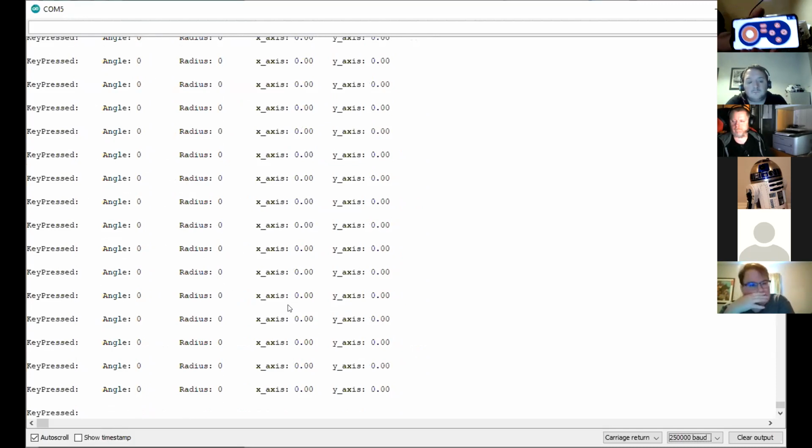So just stepping back now, all we've really done is connected 4 wires between an Arduino and a Bluetooth, loaded an app on the phone and loaded an example code. And what you've now got is a joystick that's actually controlling the Arduino. It's not doing anything at the moment, as in the Arduino is not then controlling a servo or a motor. But if you wanted to introduce Bluetooth control into any of your projects, it's very easy. There's lots of these kind of things that kick around that do that. And things like triggering sound effects or switching lights on and off are relatively simple within the Arduino infrastructure. So it's worth having a little bit of a play around with that.